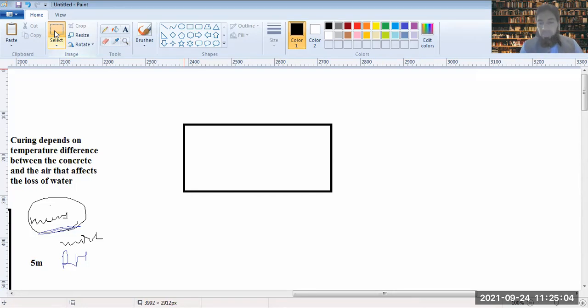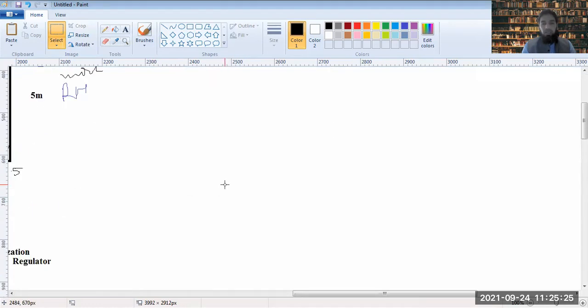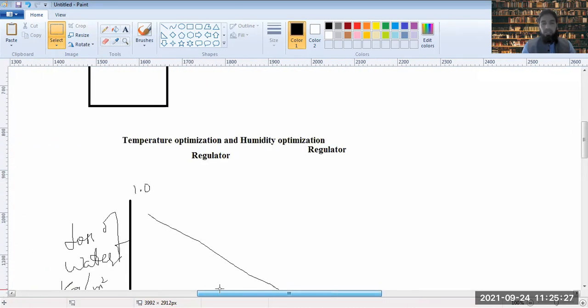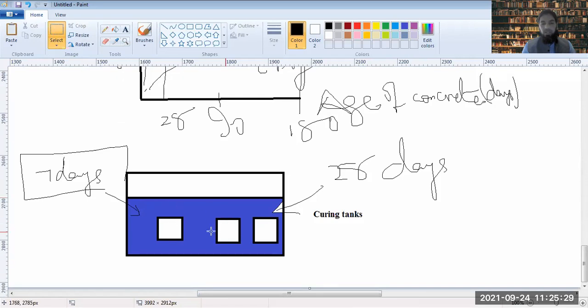We could even increase the temperature of the water beyond that if we want to do the research. For research purposes, we can keep on changing the temperature of the water and know the effect of prolonged overheating and underheating of the curing water. 100% RH is maintained in a curing tank because there is always water around it. So RH values are always around 100%.